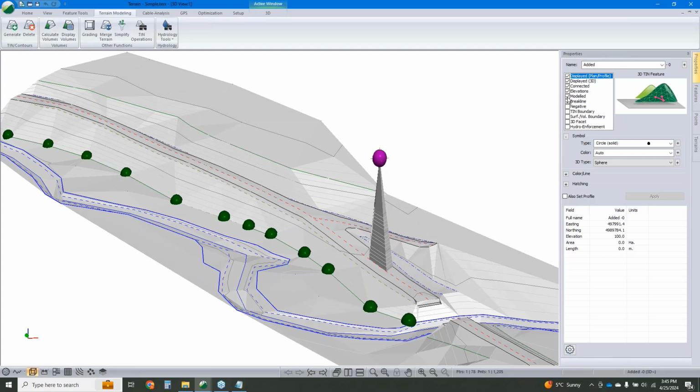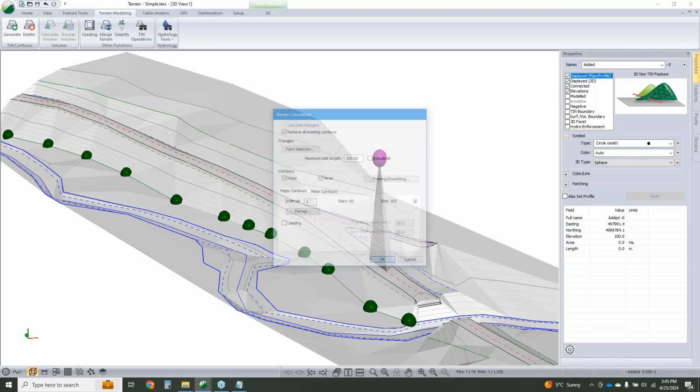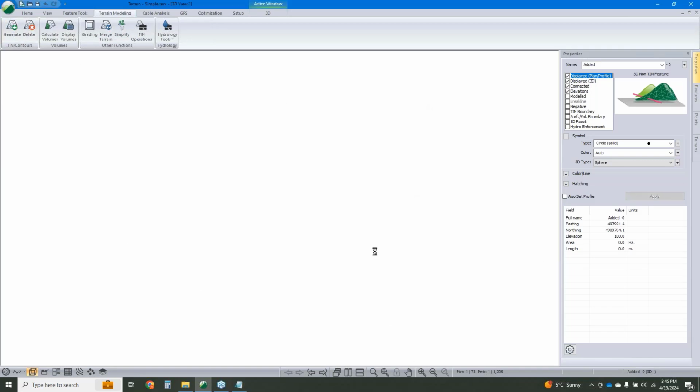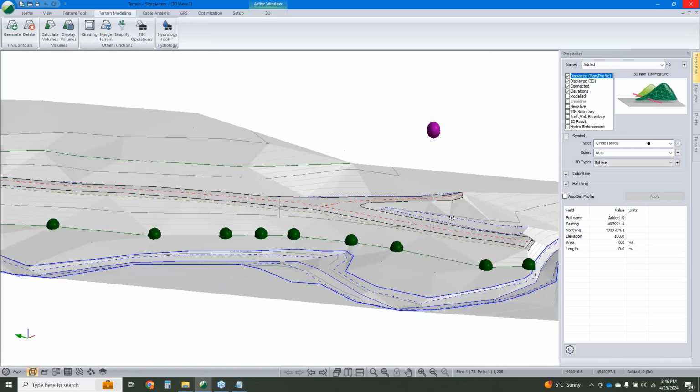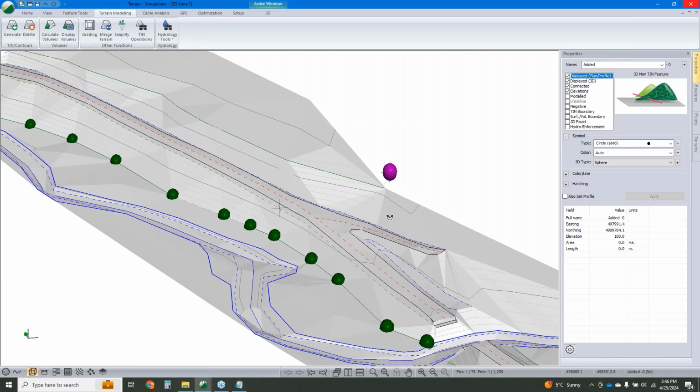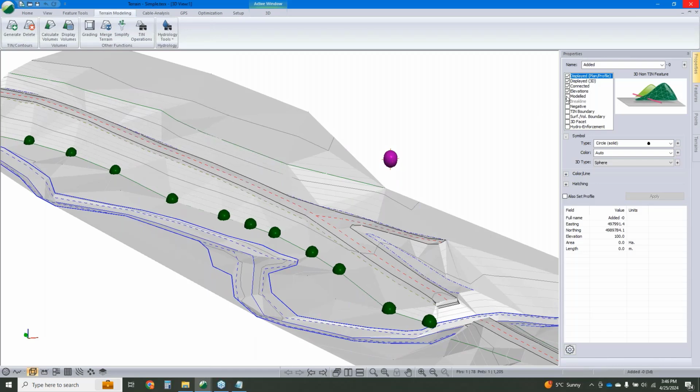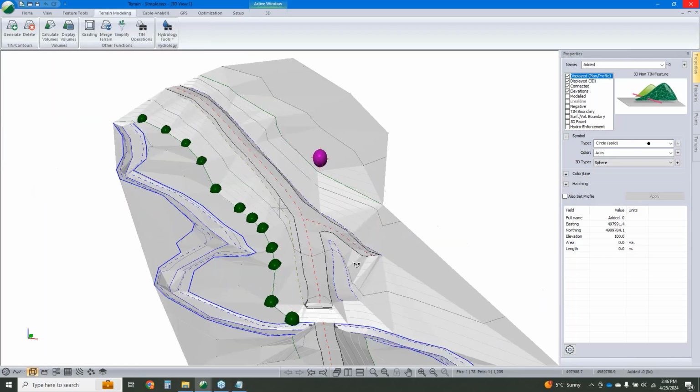Well, here we can turn off modeled. So we'll hit apply, we'll click generate. And we can see, well, here that point, since, well, it still exists, but modeled's not turned on. It's not included in our surface. And of course, we're showing it in the context of